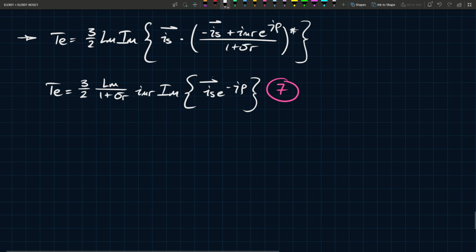So now what we can do is we can take this quantity here, and we can regard it as an expression of the stator current Is on an orthogonal coordinate system that we call the DQ frame. Now, some of you might be familiar with the DQ frame if you've studied any drives or power electronics in the past. I'll link a video in the description where we go into more detail, but for now, it suffices to say that in a standard three-phase system,